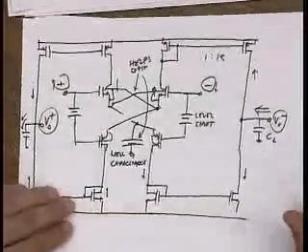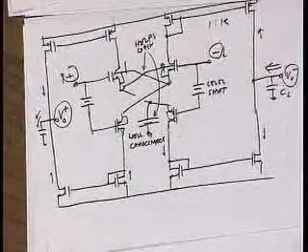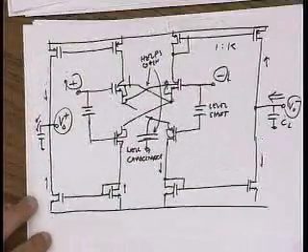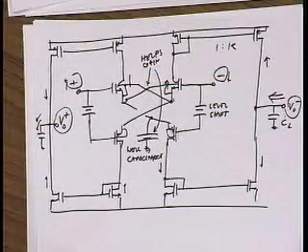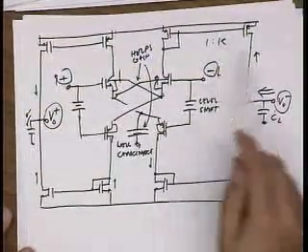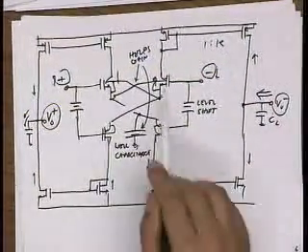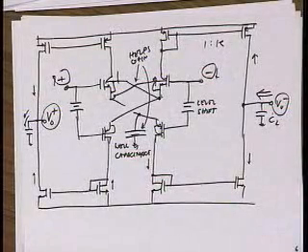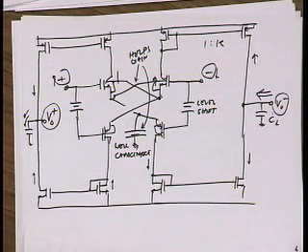Okay, so this is a great circuit, but probably won't work for your project. Why is that? Now, it looks great, right? I have a dominant pole, maybe a non-dominant pole from this current mirror, class AB input stage, really fast slewing. Why can't I use it? You should try. Maybe you can get it to work. My guess is you probably won't get it to work. Any reason?